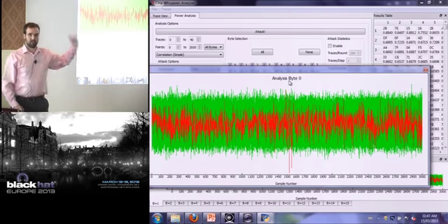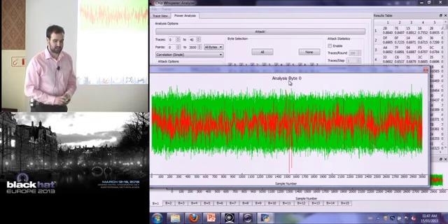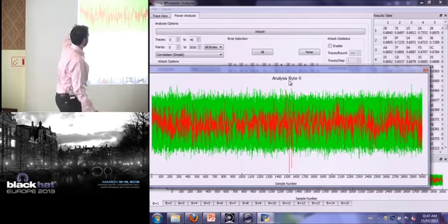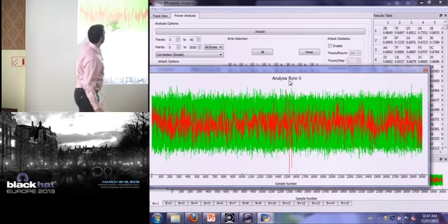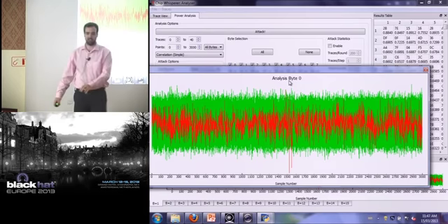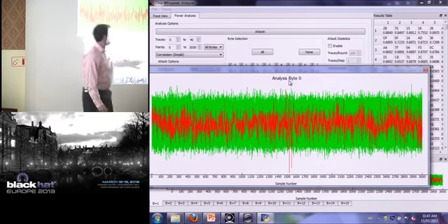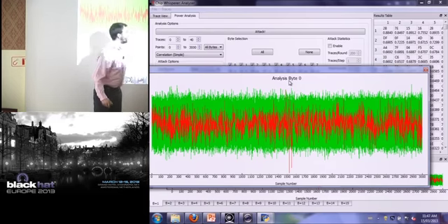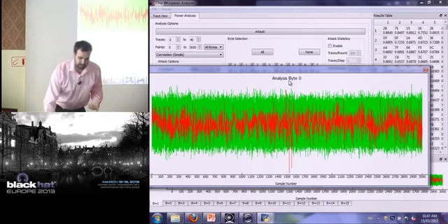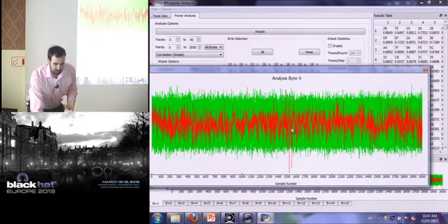So it's plotting 256 possible key guesses. And in red, it's highlighted the one that I know to be correct ahead of time because I know what this key is initially. And what we can see is that the red trace at one point all of a sudden has much higher correlation. So this is telling you that right at this point in time, this is where that operation actually occurred. So this is where the SBox lookup probably occurred.